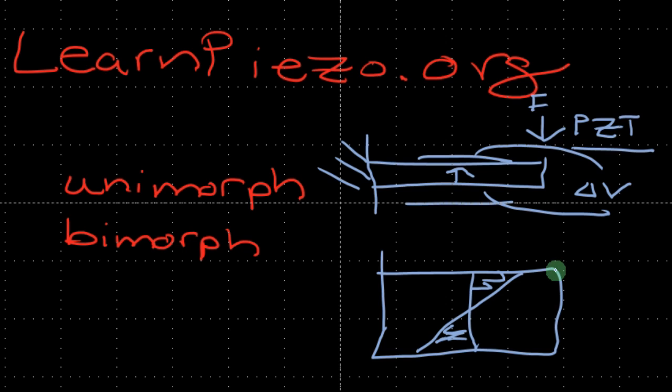If the average stress is 0, then there's going to be no voltage developed. So the average stress in this material is going to be 0, although there is local stress, which causes it to deform. So this is a cantilever piezoelectric material which is actually going to have no voltage, which is sort of weird. What is going on here? Piezoelectric material, no voltage, weird. You apply stress. I'll tell you why: it's because the average of the stress was 0.